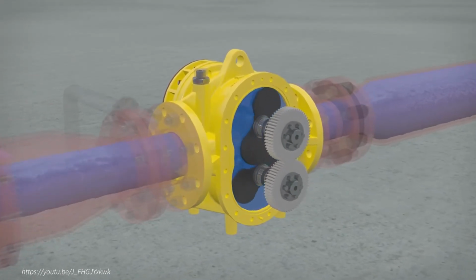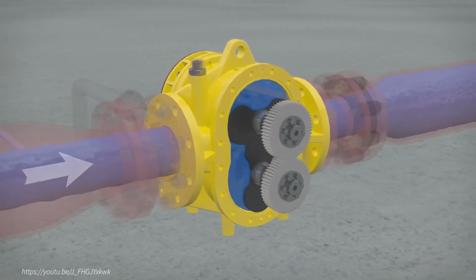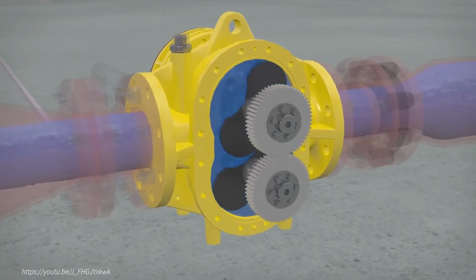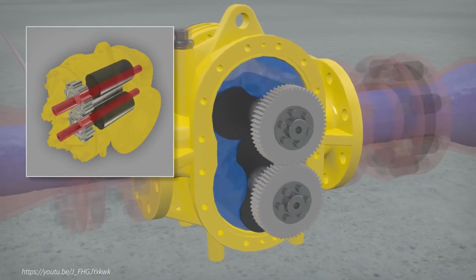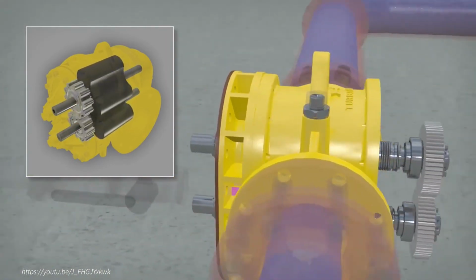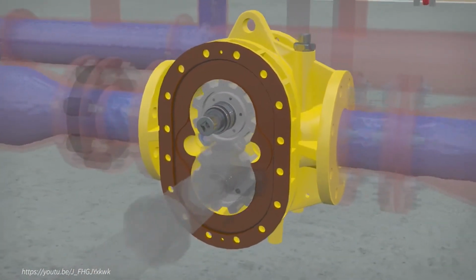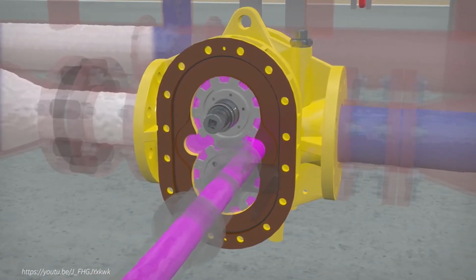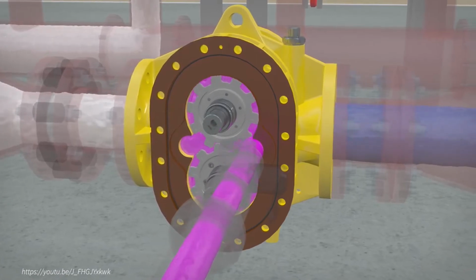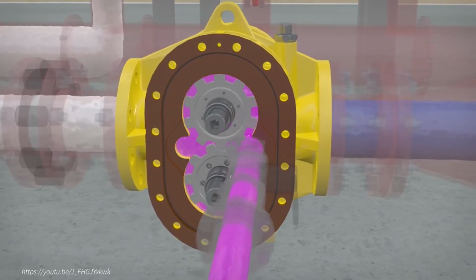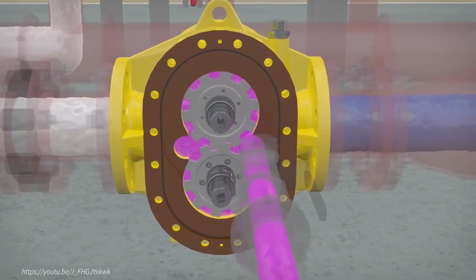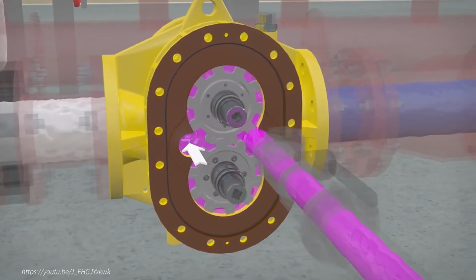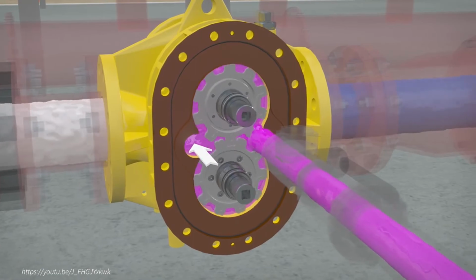The water motor is driven by the system water supply, and all water carries on to the system, so there is no wastage. The foam pump is on the same twin-shaft arrangement as the water motor and rotates at the same speed. A strong suction is created in the foam pump, which sucks foam concentrate from any available source, without the need for priming. The volume of the water motor and foam pump are directly related, with the foam pump being either 1% or 3% of the water motor.